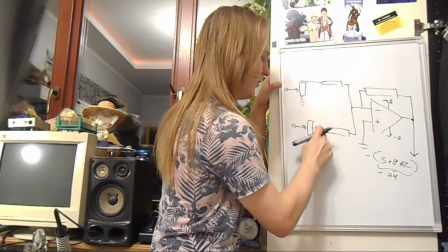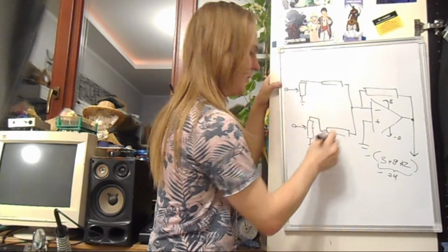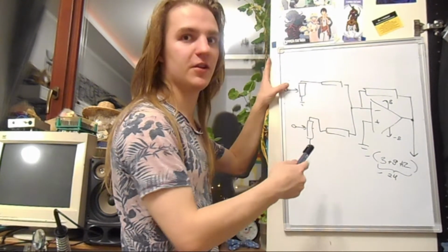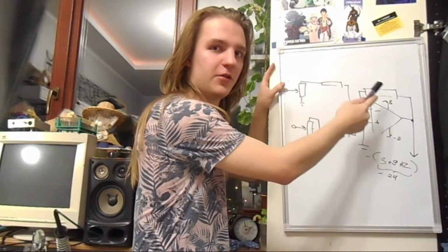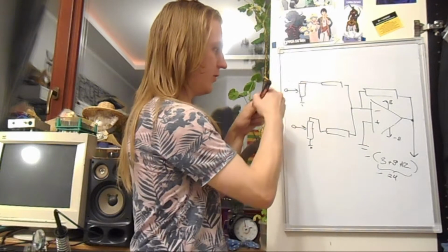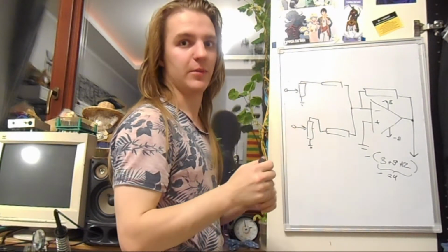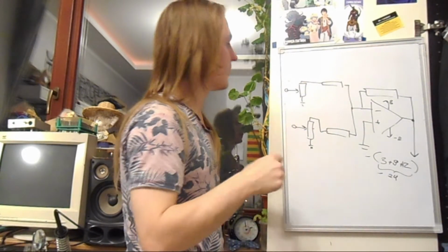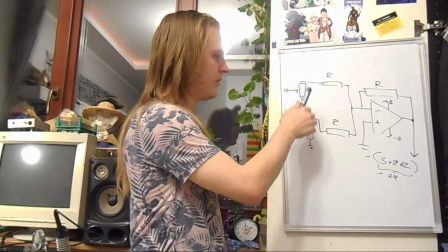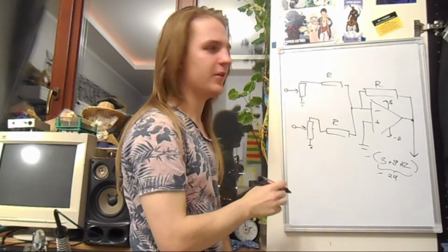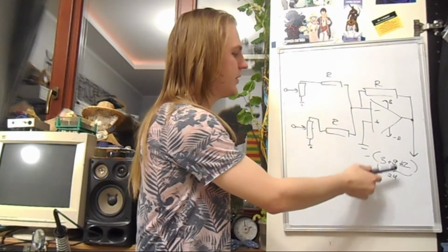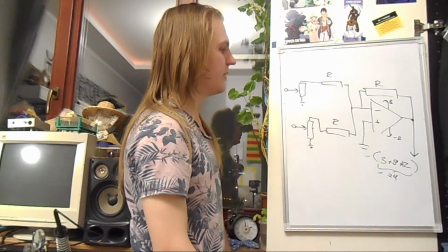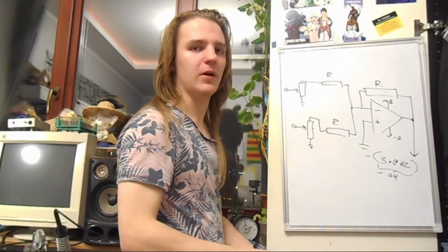Oh my god, what am I drawing? It's like this here. We choose how much of the signal goes into the ground and how much of the signal goes into the actual circuit when we turn the knob. This is our potentiometer. Google it up if you don't know what a potentiometer is. We get our values trimmed by these potentiometers and then simply summed, as we had it summed before, by the operational amplifier, and get a clean, cool, buffered mix.